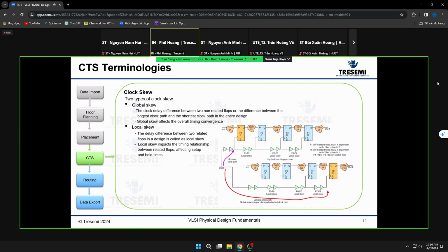The benefit is you have shorter clock trees, still good skews, but less area and less power consumption, right? So those are things you can have in mind as well. That's all I wanted to add.